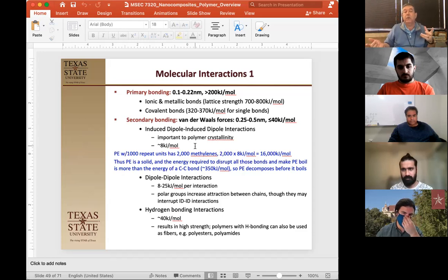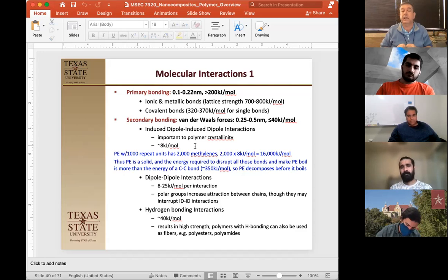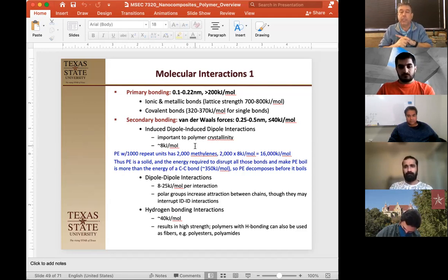Okay. But now let's go to our strongest interaction we have in secondary bonding, which is what we call hydrogen bonding. So if you have an acidic hydrogen somewhere on your system, like the polyethylene, the polyacrylic acid, the polymethacrylic acid, or the polyvinyl alcohol, those all have strong hydrogen bonding and interact with the material. If it's something that can be hydrogen bonded to, something that has a negative charge, it'll have the strongest secondary interaction that we can have.